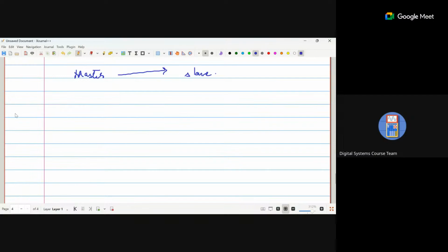So now let's talk about positive edge triggered flip flop. For positive edge trigger flip flop, your master latch will be negative latch. Okay. We will see why we have negative, and your slave will be positive latch. Let's see why it is positive and negative once we go to the diagram, the circuit, the graph.